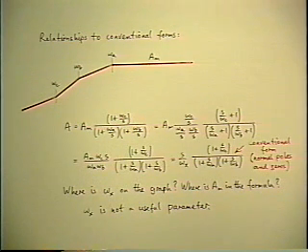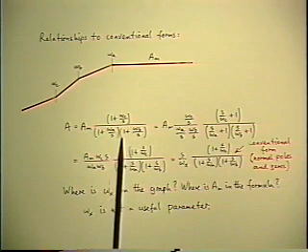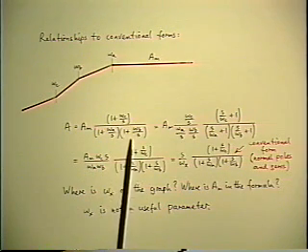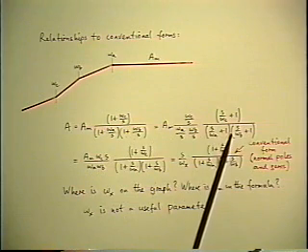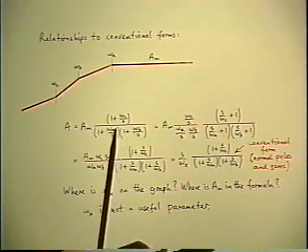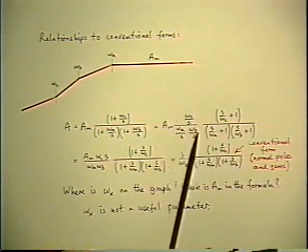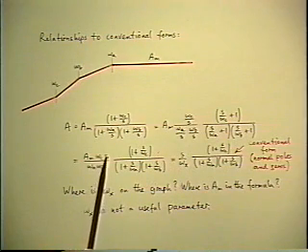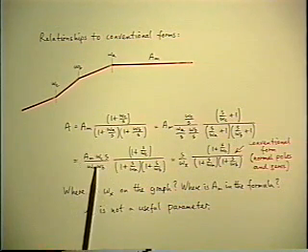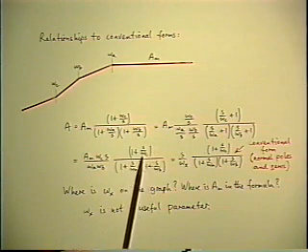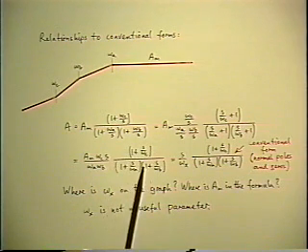But suppose you don't want to use inverted poles and zeros. You don't like them. You haven't used them before. You don't want to try them out. And you insist on writing the result in the more conventional format that has normal poles and zeros. Of course, you can do that algebraically. And all you have to do to get it into the more conventional form is pull out front the omega A over S, and the same thing with the other two. Then cancel some terms in front and collect together what's left over, which gives you this coefficient. And what is left behind now is normal poles and zeros.